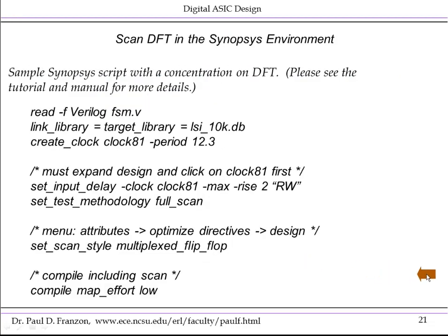Finally, I do want to cover a little bit about how design for test is done in the Synopsys environment. Remember I said it's up to you, the designer, to anticipate the test features that will have to be added to the chip. And for general logic, you actually need to account for those test features in terms of their impact on the delay of the critical paths. Thus, in general, though I don't require it in this class, you have to run at least some part of the test insertion scripts within your synthesis runs. So here I'm just illustrating what those might look like.